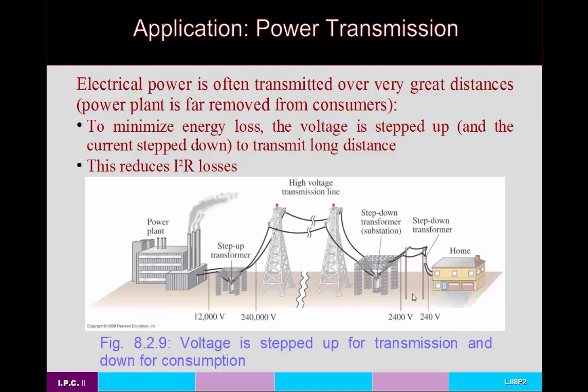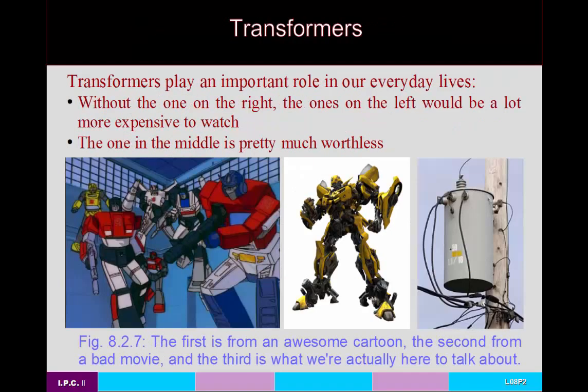And then usually from there, they go to a step-down transformer. That's the actual transformer that I pictured at the beginning of this discussion of transformers. Namely, this is the step-down transformer that goes from the 2400 volts that you're bringing in through these power lines into the 120 volts AC that you want at your house.